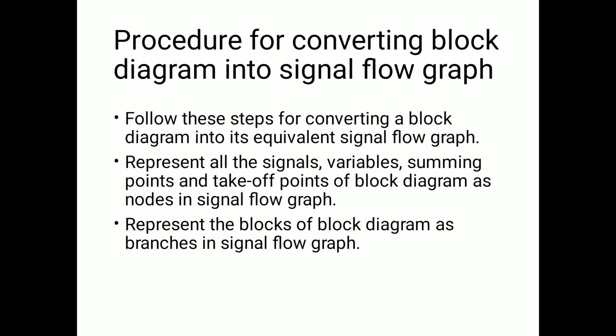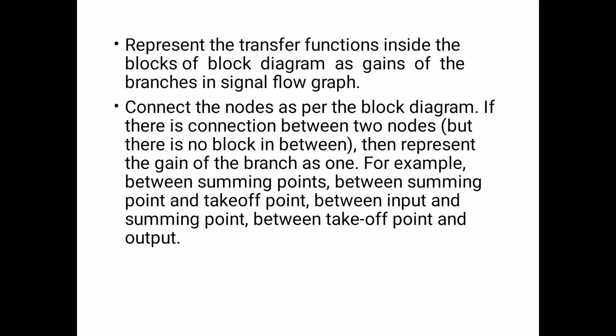Represent the blocks of block diagram as branches in signal flow graph. Represent the transfer functions inside the blocks of block diagram as gains of the branches in signal flow graph. Connect the nodes as per the block diagram.